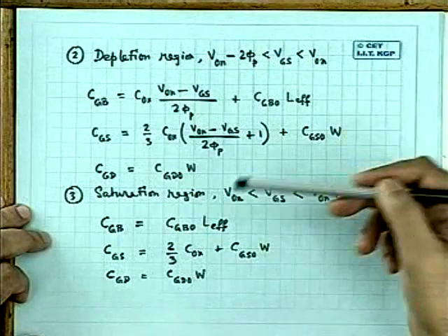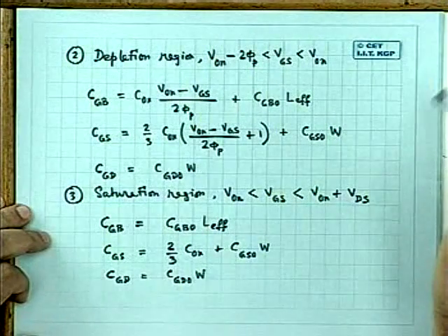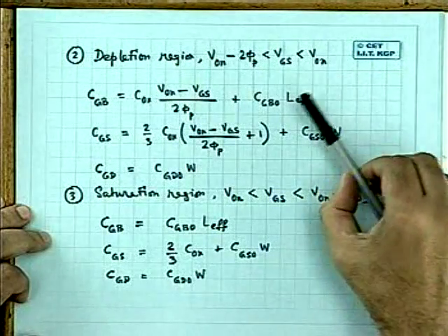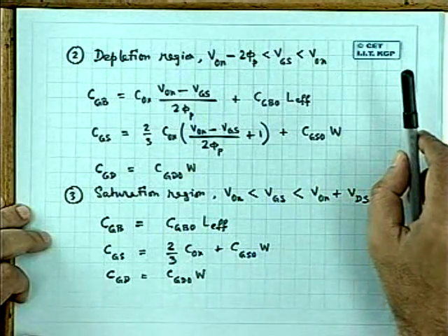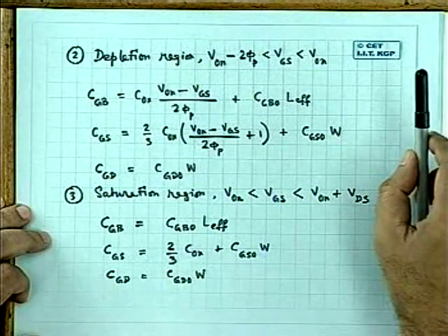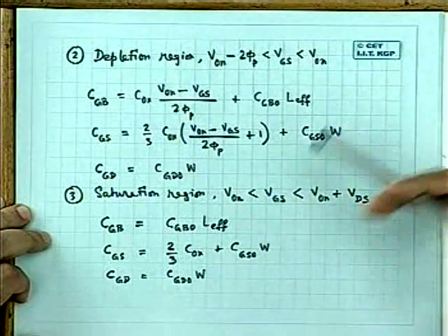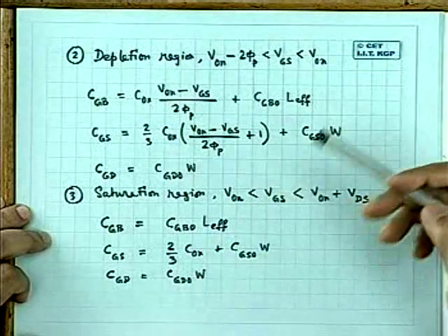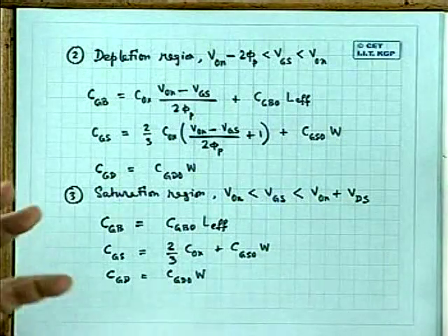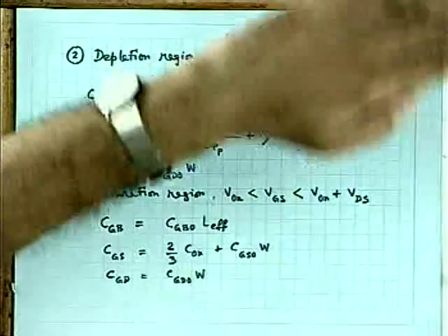In saturation region. And so what? The body actually gets isolated because of the inversion layer; the body is electrically screened from the gate. So the other effect is only the lateral penetration, that means the so-called lateral overlap.